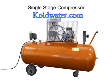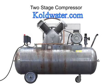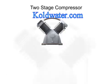As air is compressed, it becomes increasingly hot. If the air becomes too hot, not only is the compression cycle less efficient, but there is the hazard of an explosion if any hydrocarbon material, such as oil or lubricant, comes into contact with the overheated air. To avoid the hazards of overheating and still generate higher pressures, manufacturers make compressors with multiple stages.